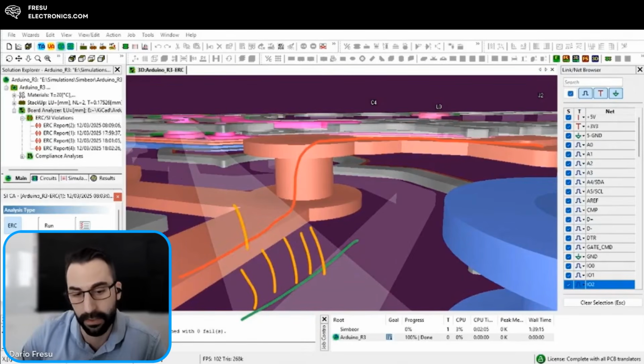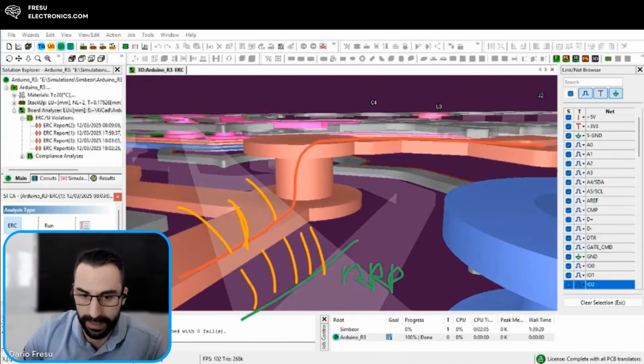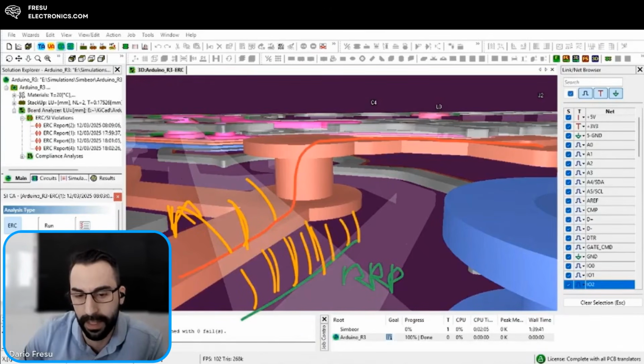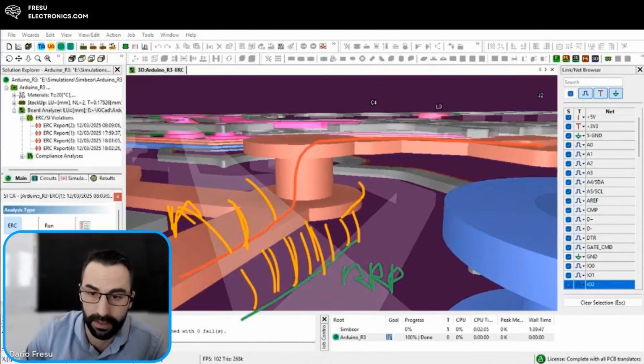Of course, I'm going to have some fields in here too, but assuming that the stackup is right and that this return reference plane I place on the bottom is close to the signal layer, then the fields will prefer to be established this way, and I have fewer fringe fields on the top. Up to this point, the fields are in here. I have the plane underneath. Then the signal now has to go up because it has to transition to the top.